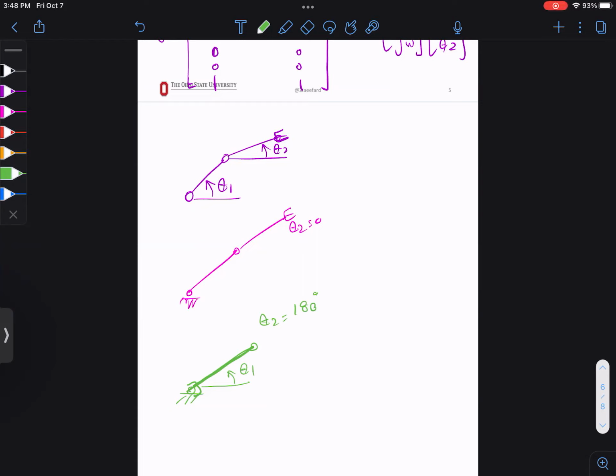Usually you will see the effect at some angles, but it's because the axes are aligned this way. No matter how much I move, these two are not moving, right? So singularity could be partial, because you say, okay, move your elbow, but I'm talking about this orientation. If this was 0, then my shoulder doesn't matter what it does, this would stay. Make sense?